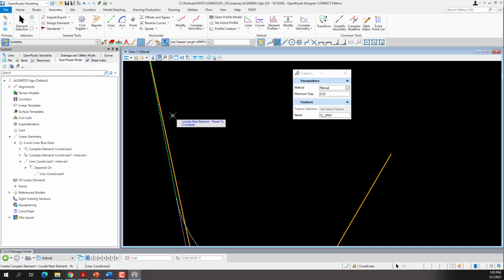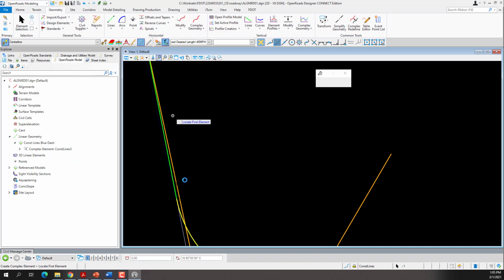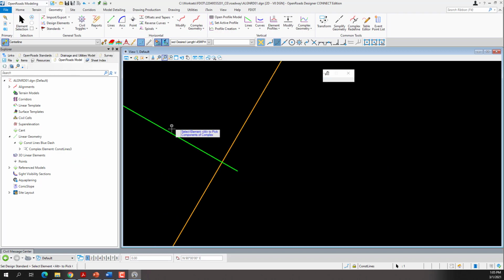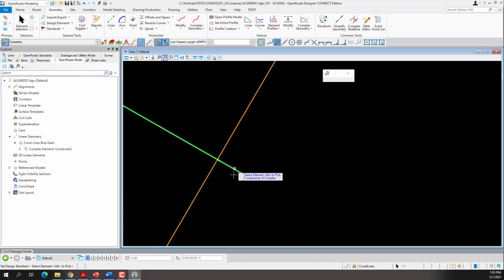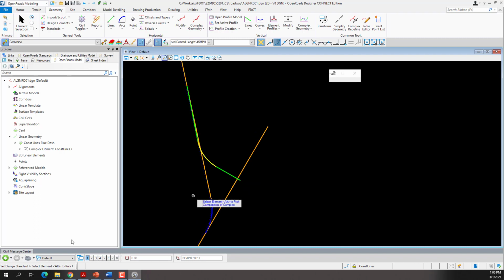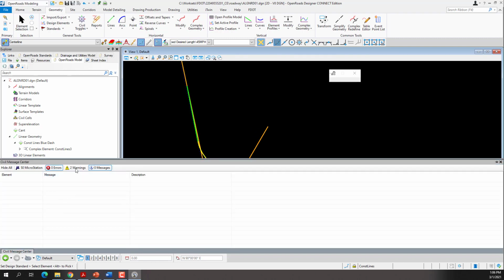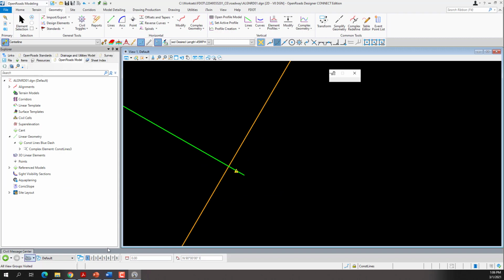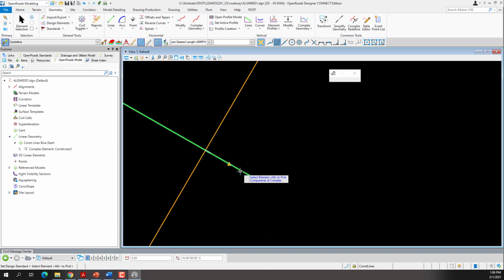I don't have any more, so I'm going to do a right click and apply. Reset. You'll notice that all our construction lines have now become center lines. It doesn't look like I set a design speed, so I'm going to toggle on set design standard, that element on there. So we may just have warnings. Oh, it did do it, so I turned the warnings off. So if you turn those on, you'll notice that this first part has a little warning on there.